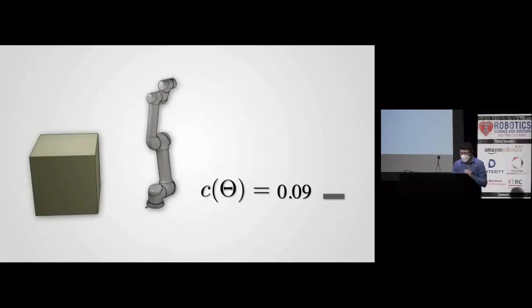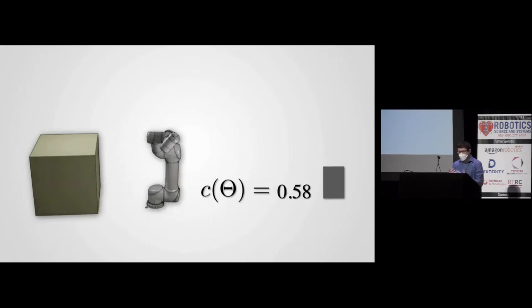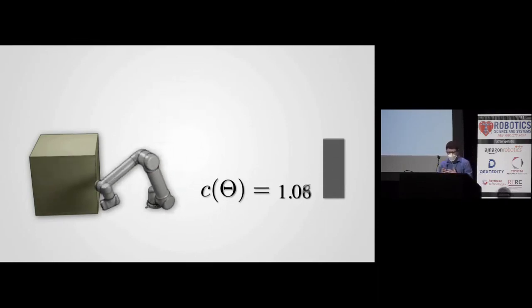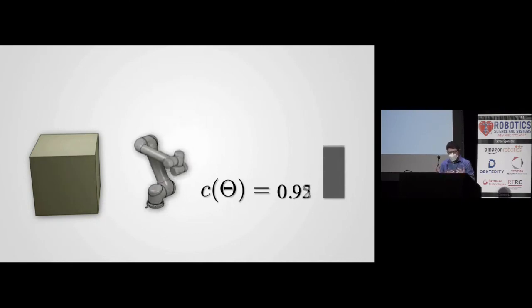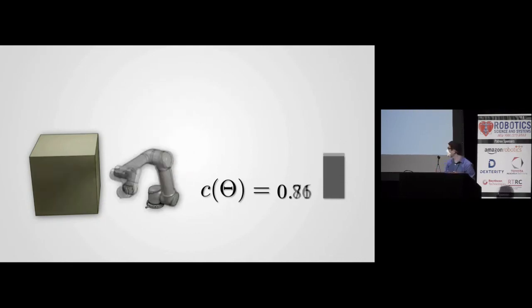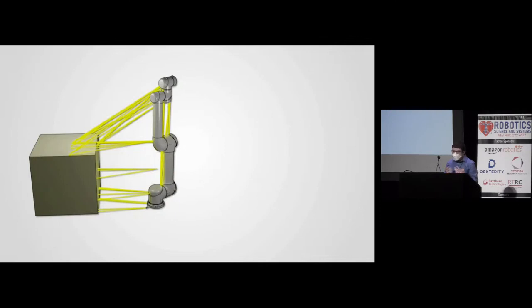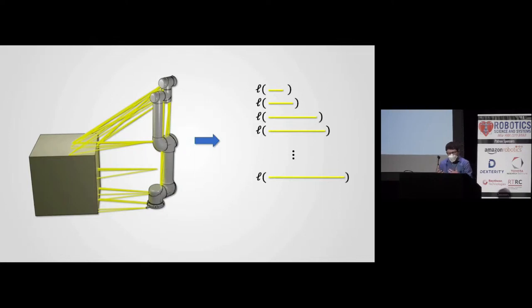Great, thank you. So a collision proximity query in robotics is a scalar function denoted as C here that characterizes how close a robot is to either a self-collision or collision with obstacles in its environment. A common way to frame this function is to take the signed distance between all pairs of rigid shapes, map these distances through some loss function, then sum up all these values to get a single collision proximity output value.